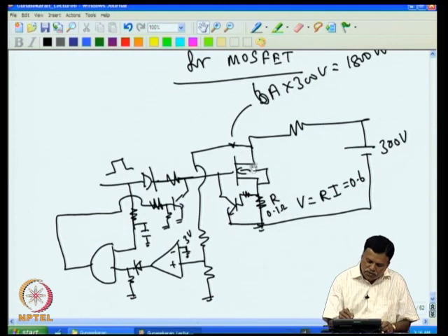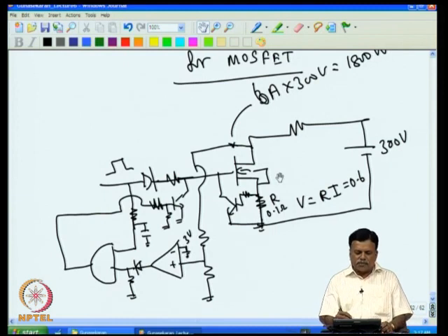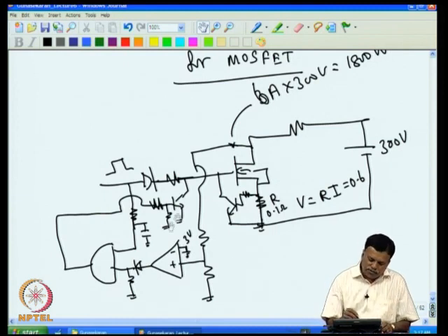By that time the MOSFET will be switched on, and once switched on, if there is no short, this voltage will be low and this will not go high, it will be on. So this will be latched permanently, that is, this arrangement will protect the MOSFET once a short occurs, and then once the short is removed it has to work.